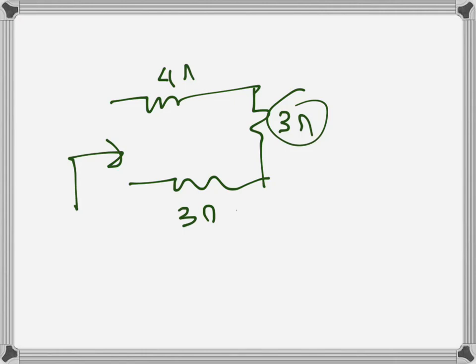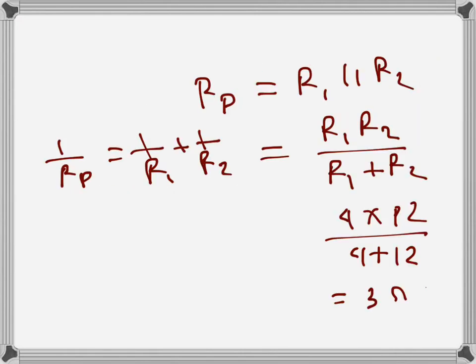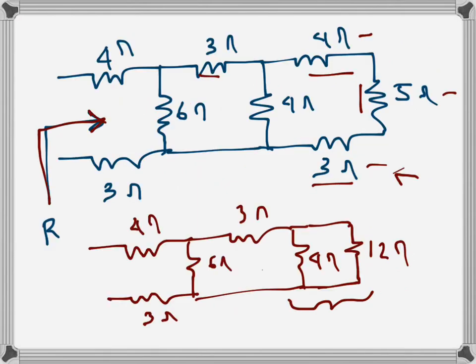So we just add these three, and that will be the equivalent resistance. The whole thing can be replaced by just one series resistance, the addition of these three, so 10 ohms. The resistance seen from here for this circuit is 10 ohms. This is how we find equivalent resistances. These are still series and parallel arrangements, but we will encounter different kinds of arrangements later as well. But this is just the series and parallel arrangements.